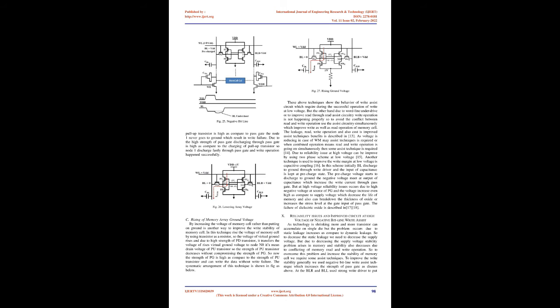Rising of memory array ground voltage. Increasing the voltage of the memory cell ground, rather than putting it on ground, is another way to improve the write stability of the memory cell.